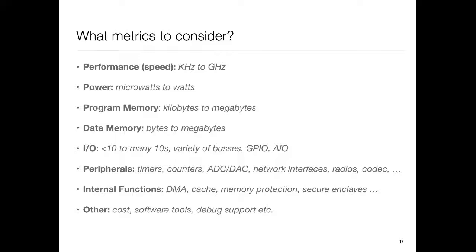But if you look at the complexity of those units, they are actually far more than the smaller processors, so not viable. Memory protection in MCUs is usually non-existent. That is, everything is operating in the same physical memory space. There is no virtual memory. So if something goes wrong in program 1, it will crash program 2.